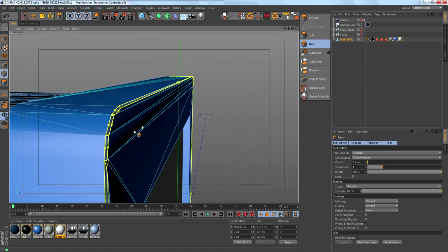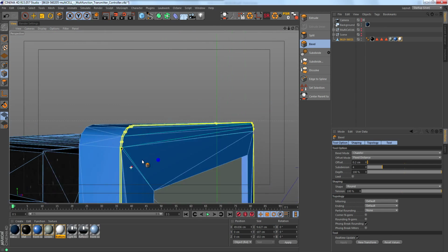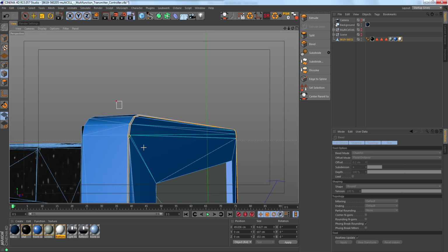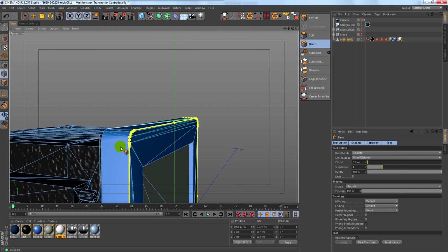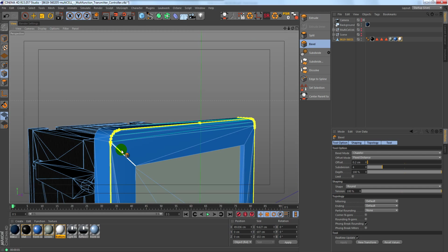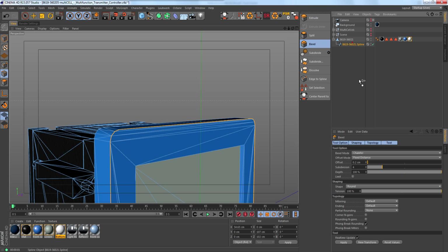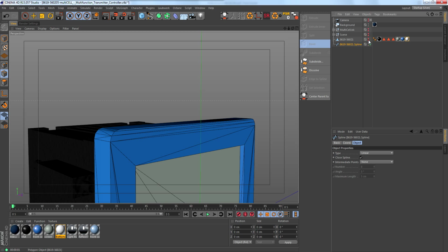And you can see that's not working for us. Nope, that is not working at all. And that's just because it's a CAD file. There's lots of triangles. It just can't interpolate it correctly. So let's undo that. Let's click this edge to spline and get this out. And let's hide our model.